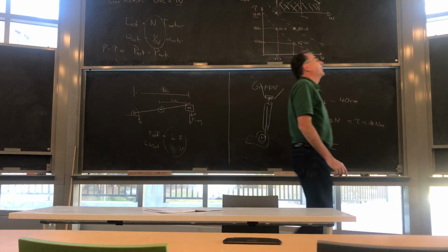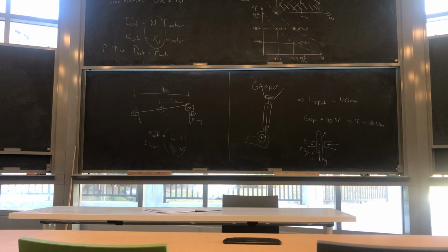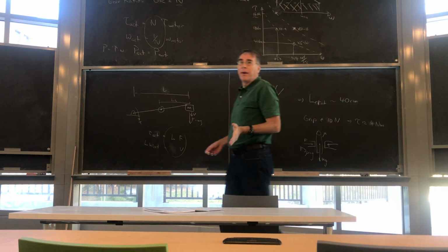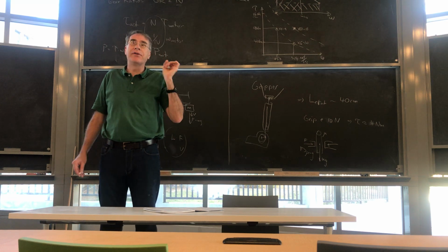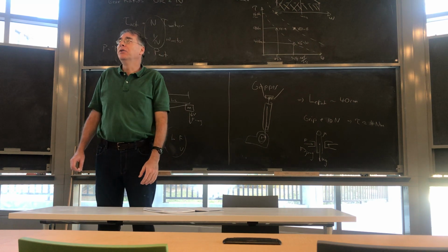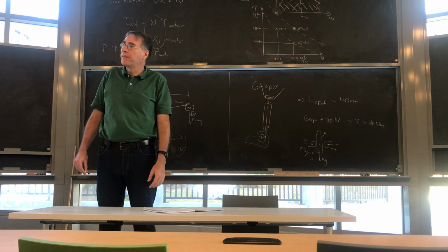So this is their spec sheet. They've got a peak torque and continuous. If you look at the X54s, it's 4 newton meters, and the X59 is 9 newton meters continuous. So you can hold that forever. The problem is it heats up, and that's what ultimately limits it. For a brief moment in time, you can stick a lot more current in it and get more out. Usually that's on the order of a second or so.